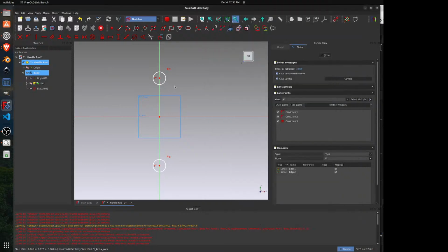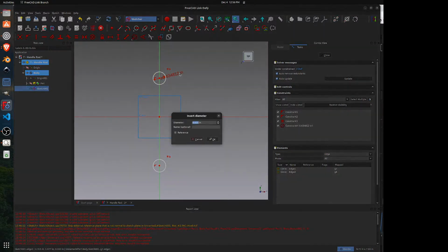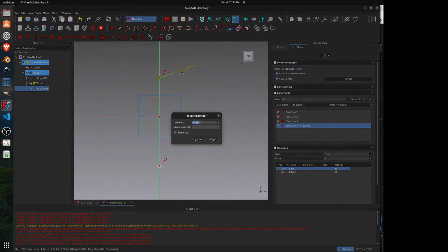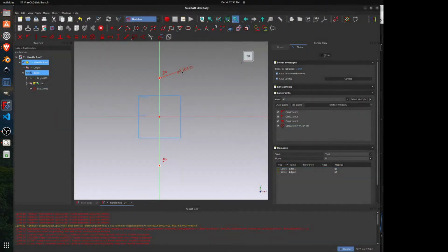And so anyway, now that I get these two holes, the diameter of them, again, a number 37, I'm going to guess is somewhere, without looking it up, around, maybe let's just call it 3/16 of an inch or something. I'm just going to pick that and make it 0.1875 inches. So those two, you see, they both shrank. Oh, thank you. All right, I'll make it what it should be. 0.104. All right, thanks for the help there.